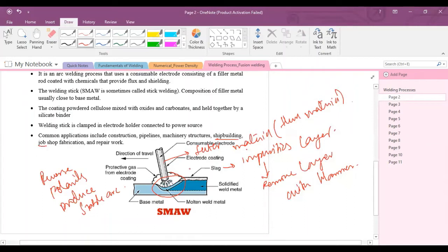During the welding, filler material will also melt and deposit over the surface of the molten pool, or add into the metal pool, and form a slag. After welding and solidification, this slag will be removed from the surface. Sometimes, in a non-ideal case, this slag will react with the oxides and form an impurities layer, and these impurities can be removed with the help of a hammer.